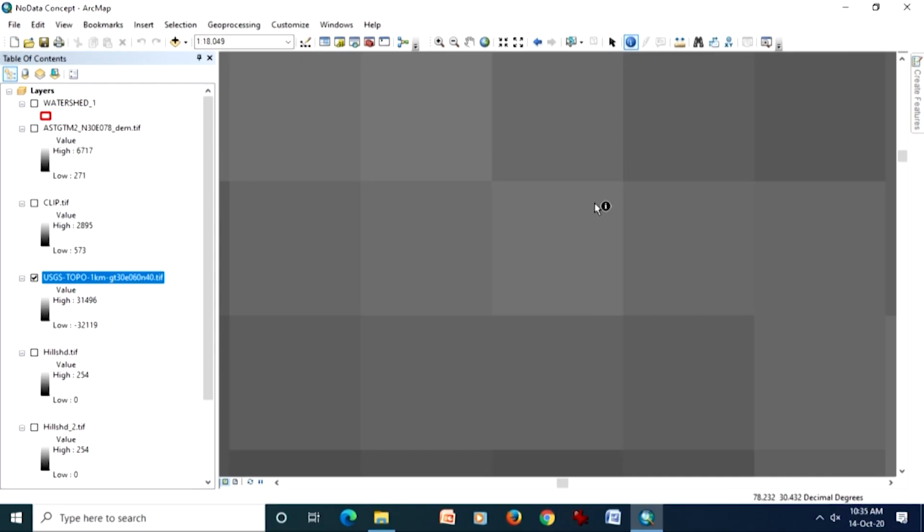Now, since we have digital elevation models available at 90 meter like SRTM, we can very well download for our area of interest, or 30 meter, or even nowadays you can get 12 meter. For India, you can also get Cartosat based digital elevation model of even up to 5 meter resolution. But only a few tiles are available for India.